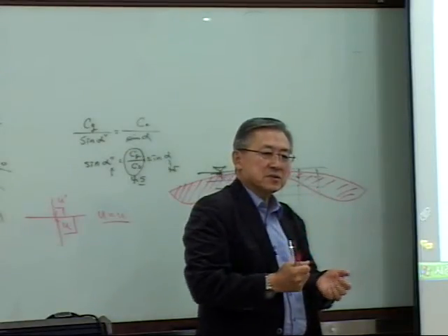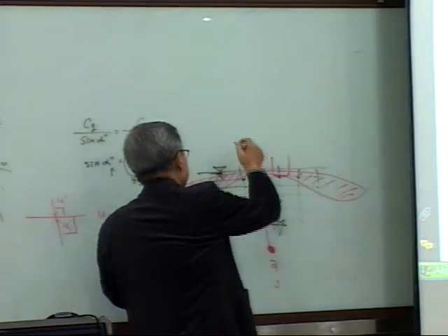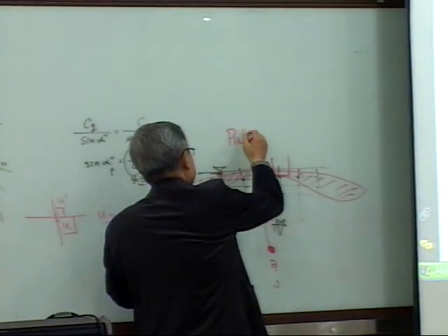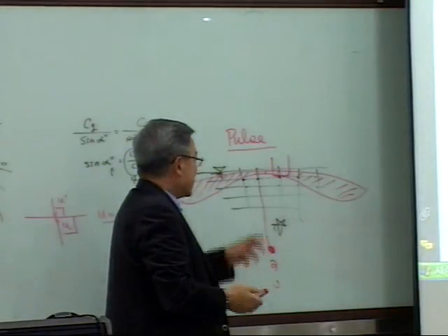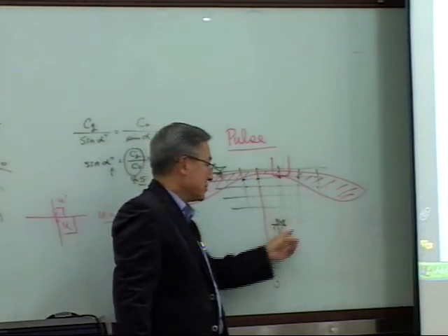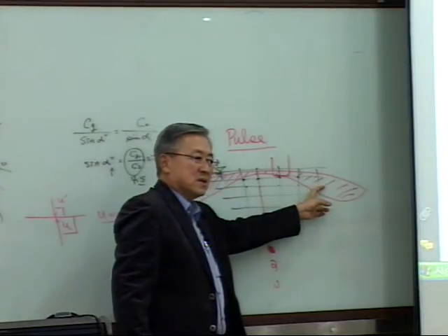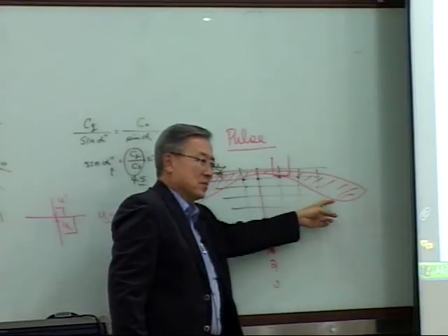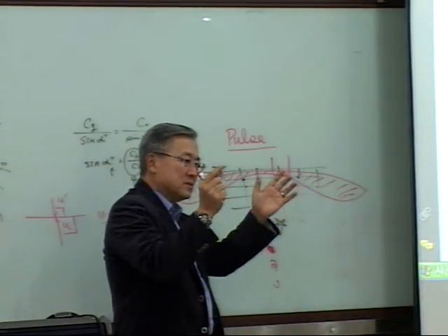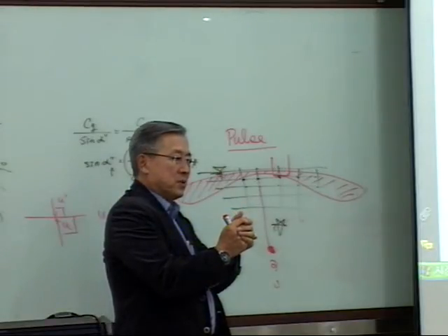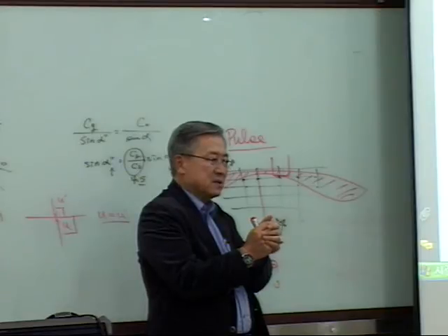Anything that collapses in the water produces a pulse. It's a secondary shock. So now due to the explosion, a cavitation zone occurs. It cannot sustain in the water because the water pressure is all around, so it has to close. Anything closed has a closure pulse. It's not big, but cannot neglect it.